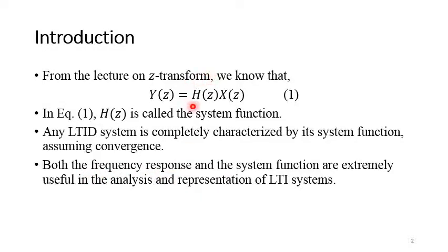Similarly, taking the Z transform of the impulse response will result in the system function or the transfer function. So both the frequency response and the system function are extremely useful in analysis and representation of LTI systems.